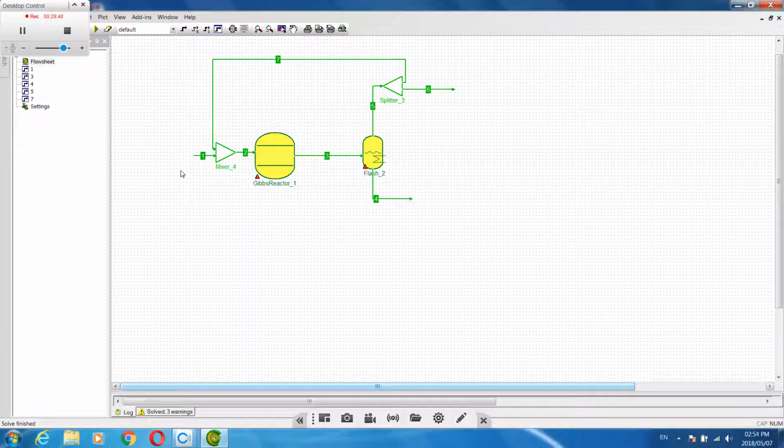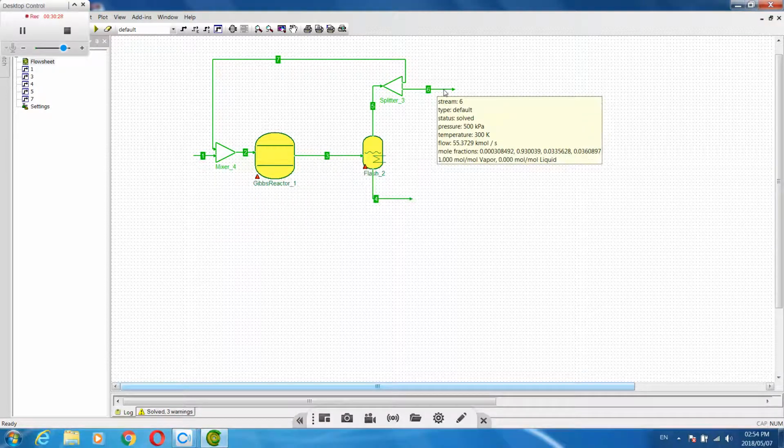So what we did, we had a feed into the reactor, we didn't have all this. Then the simulation software calculated everything based on the temperatures given. Then we had the product. Then we had a flash where we separated the vapor and have much of the ethanol down in stream 4. Then here we had a purge to avoid the build-up of the inert. If we've got 2 moles of inert coming in, 2 moles must come out, to be at steady state.